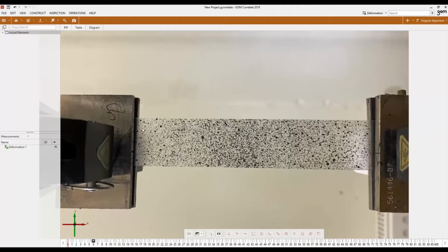Now we will define surface component. This is something that will divide this whole domain into small squares, and it will also have some overlapping squares. And as this specimen moves, those squares will move, and from those movements it will calculate the displacement field, and from that the strain field and every other output that you request.